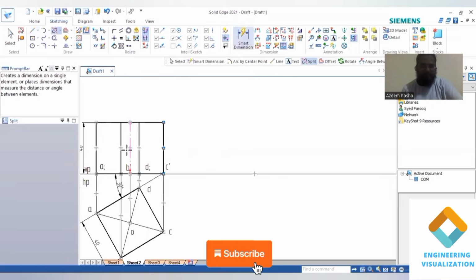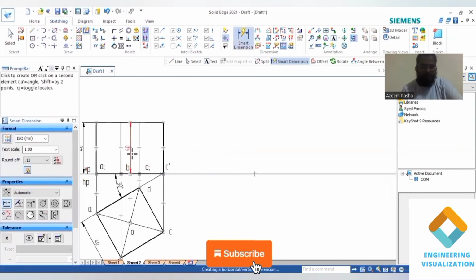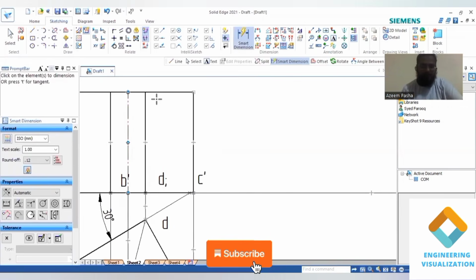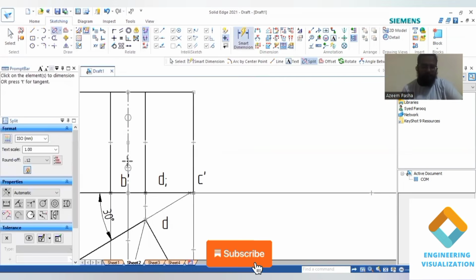axis, because we have to draw an angle line exactly at the middle point of it. So we need to split it exactly at the half here. Use the split command, click on the axis and click on the midpoint. So it will get split into two halves. You can show the dimension for the lower part, so it will be exactly 20 mm.